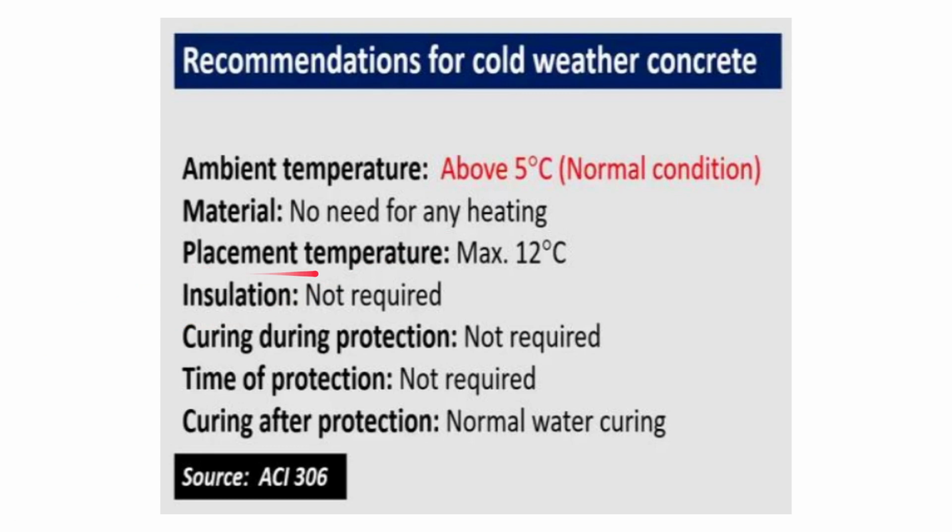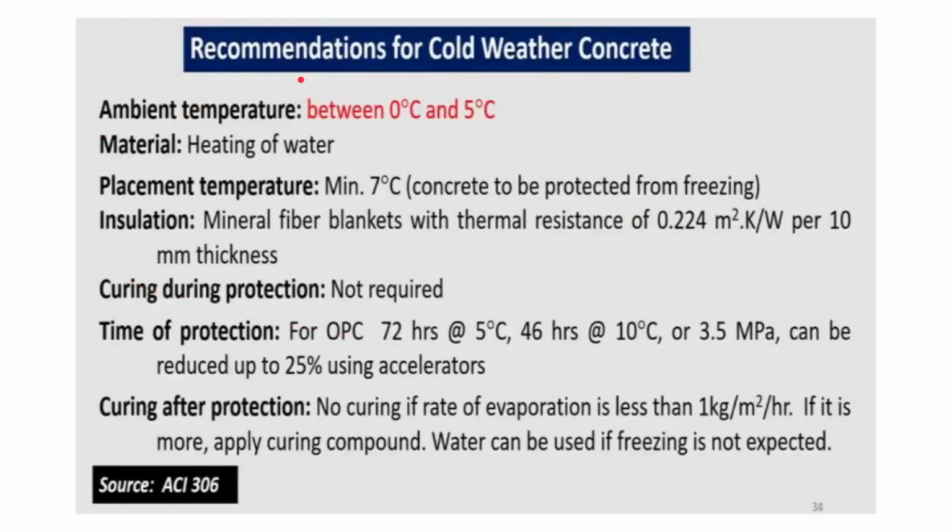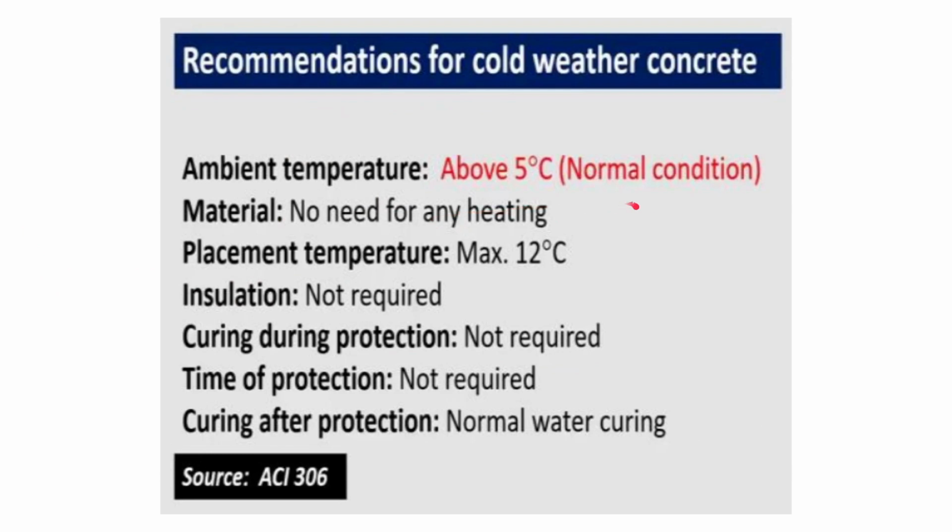Placement temperature should be a maximum of 12 degrees centigrade, and if these two conditions are true, then insulation is not required, curing during protection is not required, protection time is also not required, and after protection the curing can be normal water curing. So nothing special will be required, and it will all be normal if the ambient temperature is above 5 degrees, and placement temperature is a maximum of 12 degrees. So that is the thing, if above 5 degrees.